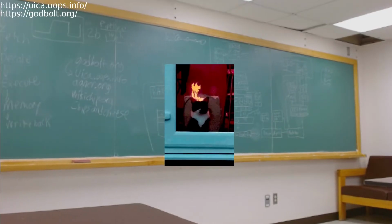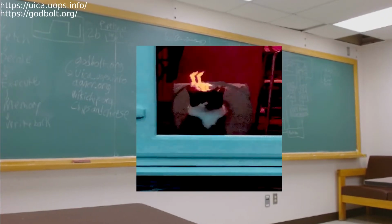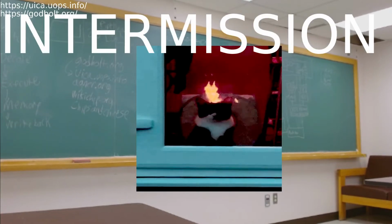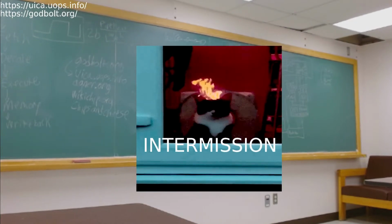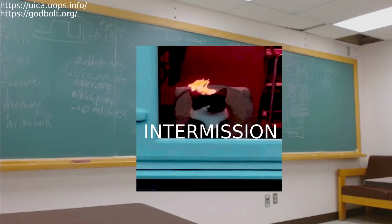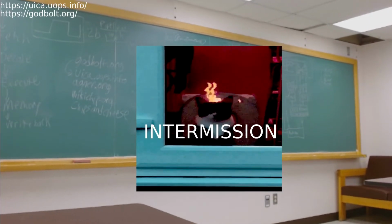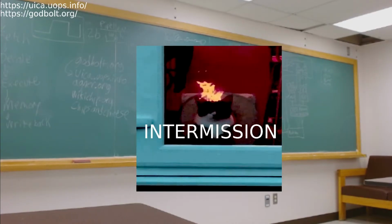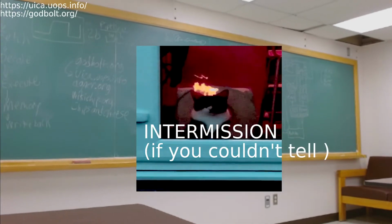Also, what's that AGU component? I just realized, AGU is the address generation unit. It calculates based off of the registers where you're trying to access, and then also handles stores and stuff. Also, I can give you a couple of examples of what gets decoded within the complex decoder. For example, add with carry or vectorized move. Those are the two I can remember that will get decoded in there.